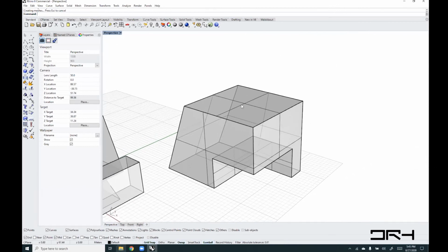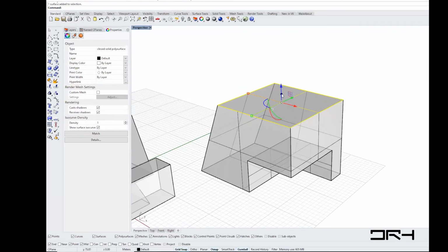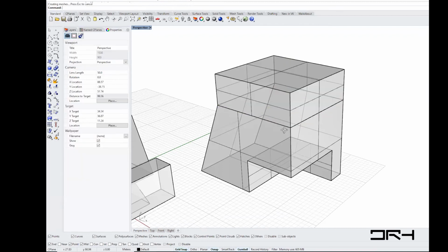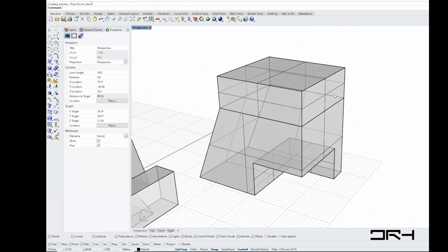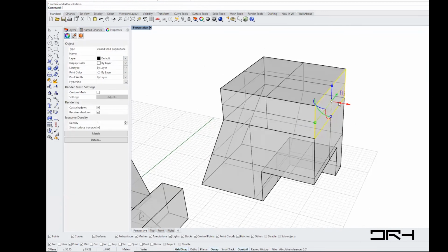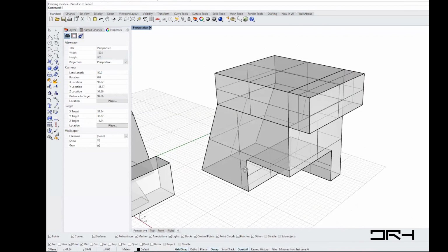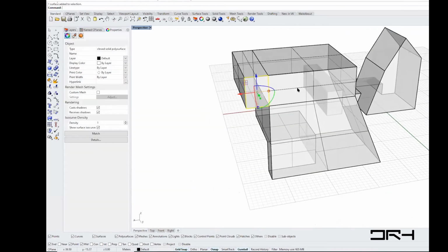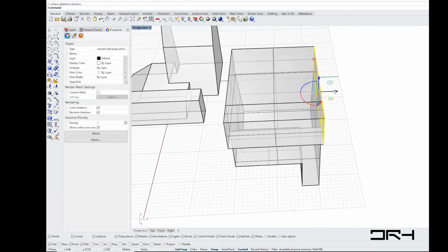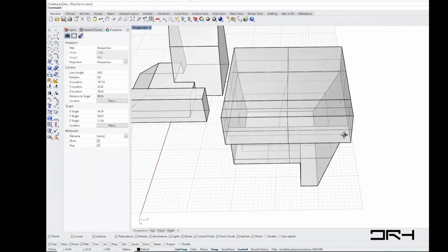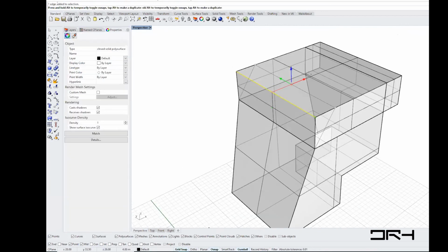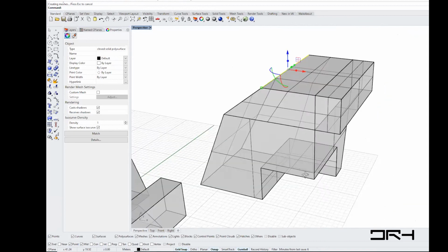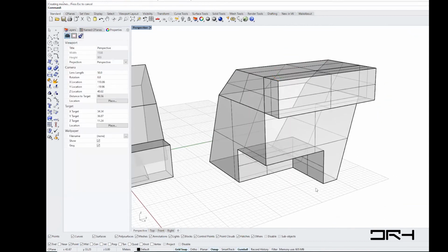Some of the fun things that you can do is extruding as well. So you can select that face, but if you click on the sphere, you can extrude up. So I'm not just moving the face, I'm now extruding. And now you can quickly start to expand your object to have cantilevers or what have you here. I can move that in this case. And you start to have these kinds of situations. So yeah, that's the sub-object selection.